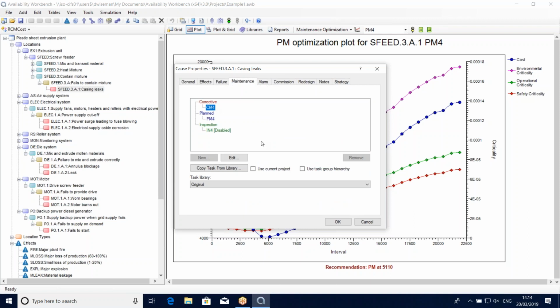On the other hand, I can do condition monitoring, do a condition inspection where I can check my equipment while it's still working and look for signs that failure might be imminent. So that might be like a vibration inspection or checking for hot spots or cracks in a casing. And then if you spot that there's a problem developing, you can stop it from causing an outage by maybe intercepting that failure before it happens.